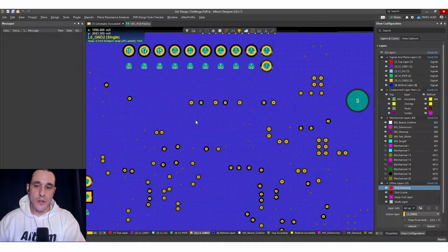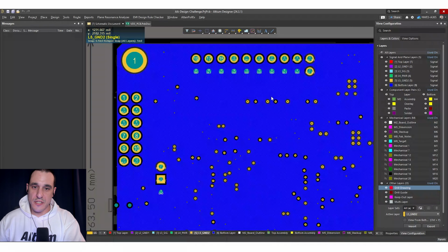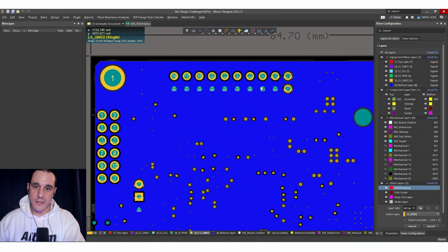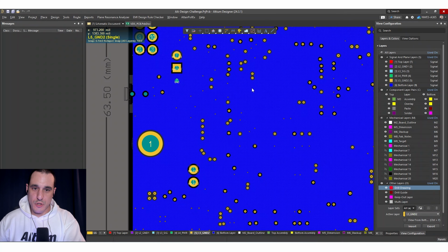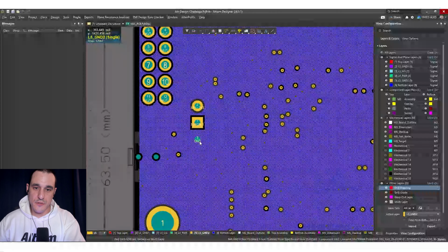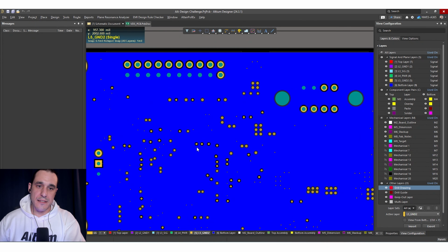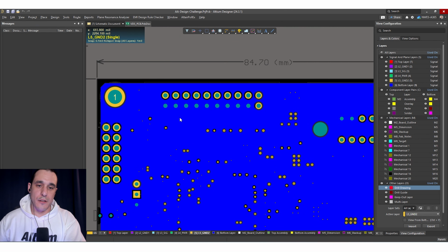You don't need to do it on all the vias, but on these headers, definitely should do it. So whenever you have these ground connections, particularly on this component, and I'm sure you can find some others if you zoom through here, such as right here on this switch, I would say apply the thermal relief, and that will aid through hole soldering when this board goes into assembly.